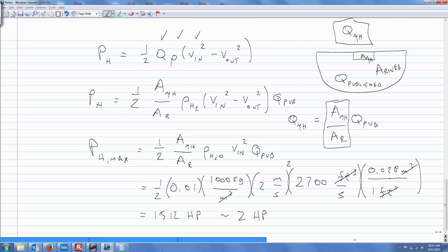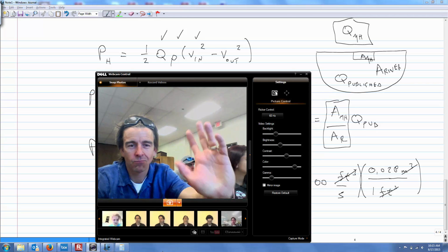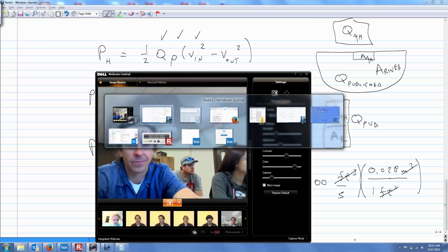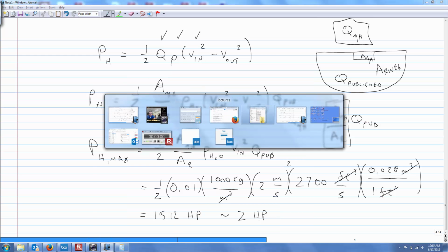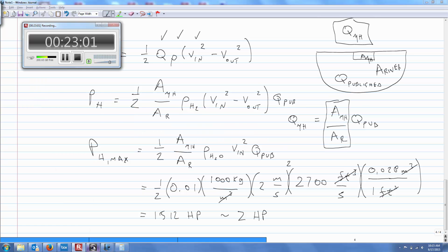And use those numbers compared to how fast it is going to spin with all the pulleys, or how fast it is going to spin, theoretically, with that propeller. Now that you have these numbers, you should be able to figure out an RPM, or design a blade to give you the desired RPM. And what is your desired RPM? It's probably about 1,600 to 1,800 RPMs on the propeller. I don't know exactly. You're going to have to figure that out.